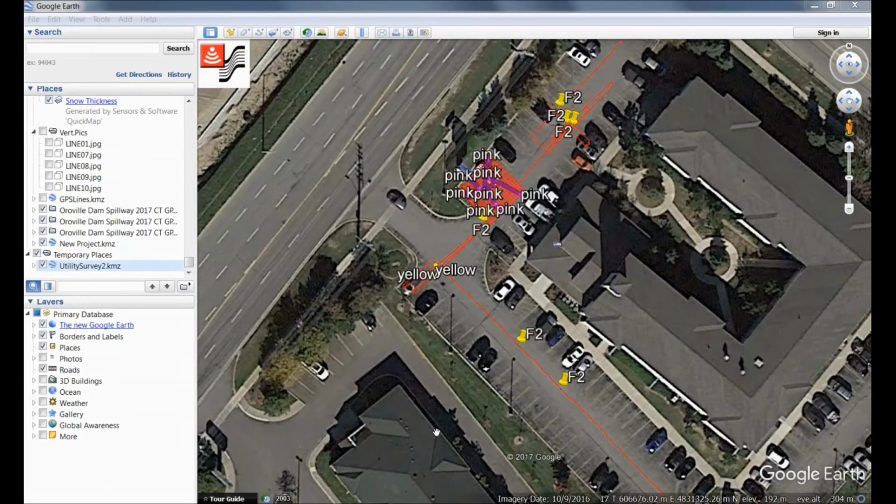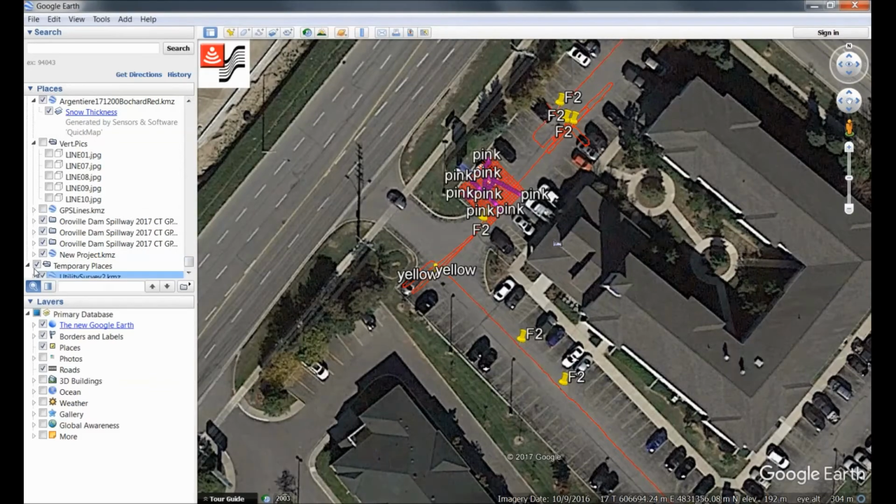Back to Google Earth. Now, this is not detailed training on how to use Google Earth, but I can show you a few things that might be helpful when looking at your GPR data. A Google Earth KMZ file consists of several layers that can be turned off or on. To see these layers, go to the name of the KMZ file you just created in the Places window on the left, and click on the arrow beside it to open the KMZ file and see the sublayers.